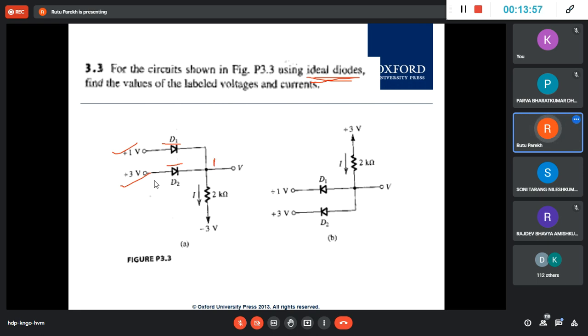Yes. But ma'am, how can we say that it is forward bias, because we don't know the V? That's what you have to find out. So we have to find out V across the terminals, okay? So now here this is minus 3 volt. So what it means is across the ground. Okay, and a battery, so this is minus 3. But in this case, both D1 and D2 will be forward biased. So you have to find out voltage between this point and this point. That's what it means. Similarly, for here also, we say, right?